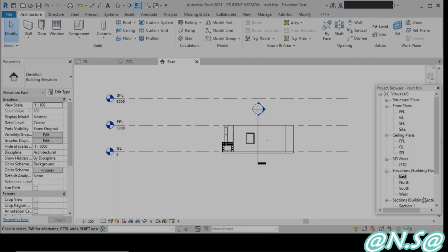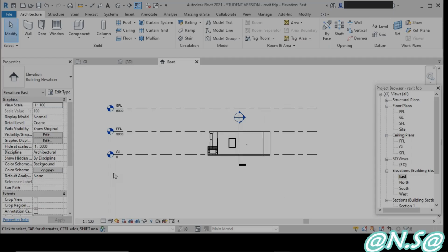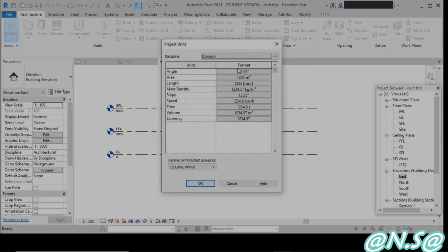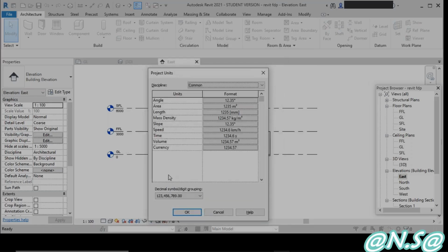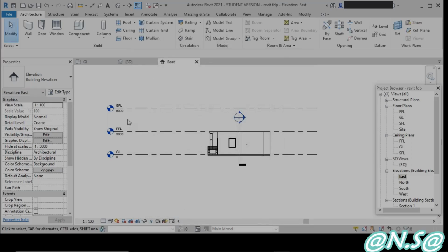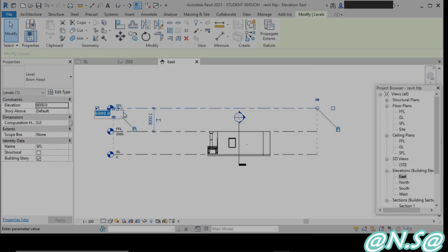How do you set units in this? Yeah, units we have already discussed in the first session. Initially, we need to set the units here. So look at this, length units in mm. So wherever in the project, whatever value you enter, it will be taken in mm only. Even suppose if it is 6 meters, instead of 6 meters I just go with 7.